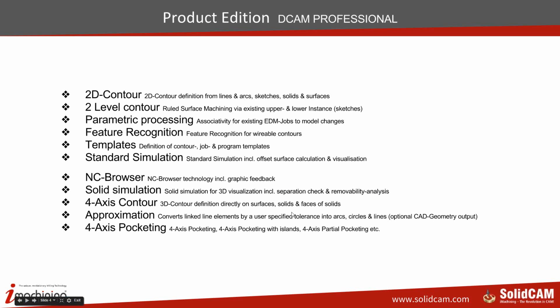The next one will be solid simulation, which can show you actually your stock and your 3D contour that runs around your stock, so you can see actual cutting. Also inside the solid simulation, you can see your devices attached on your EDM machine, such as the rotational axis inside erosive grinding and your table inside multi-axis EDMing.